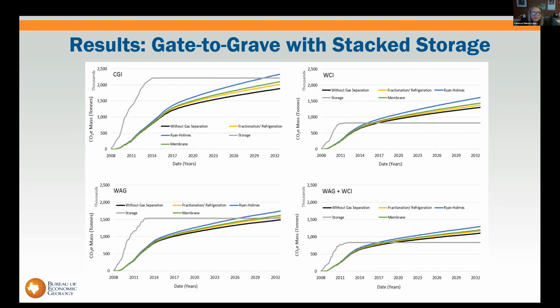And so in this case, the excess CO2 is injected into an underlying saline aquifer when the amount of CO2 recycled surpasses the volume that is intended to be injected into the oil field. Normally that CO2 goes to a different CO2 injection pattern or even a different CO2-EOR operation.